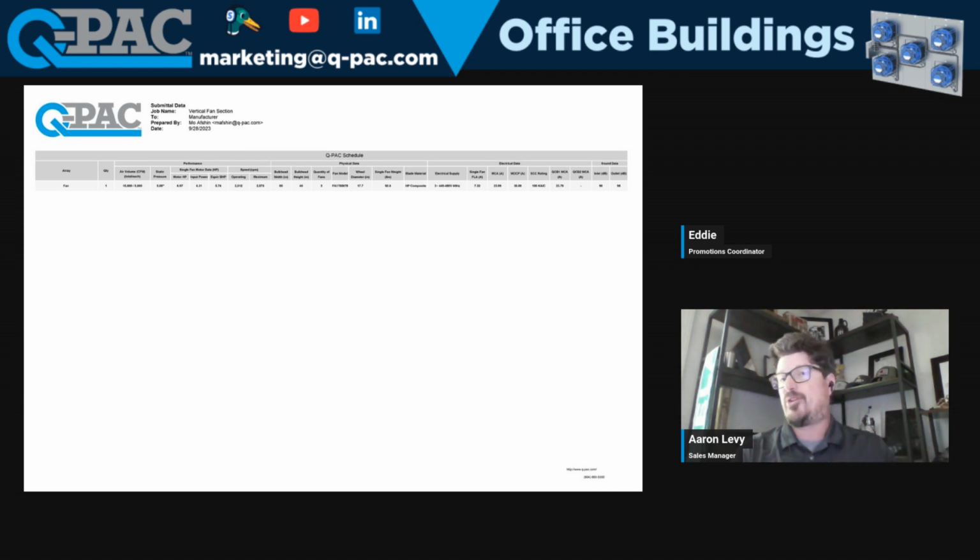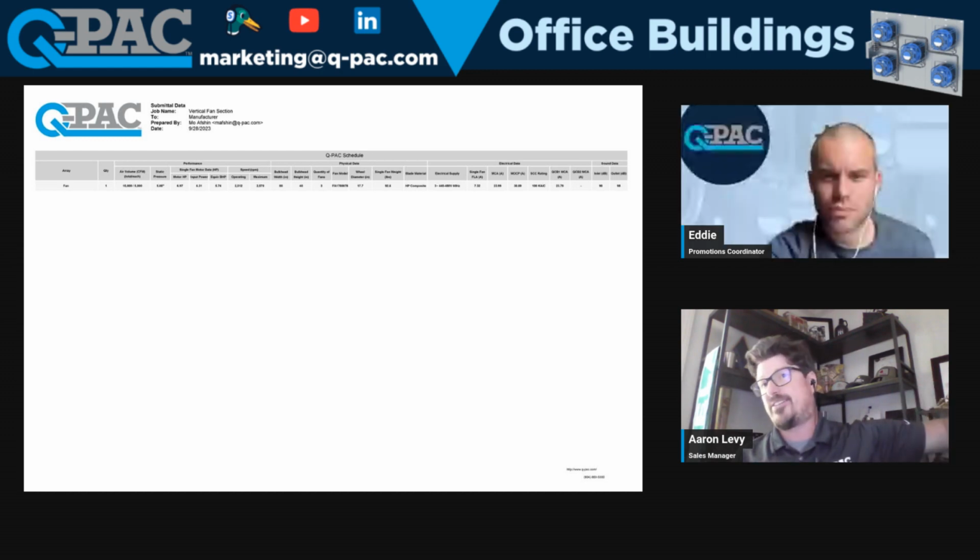It really depends on how many quick connect boxes you have. So as long as, let's say, you have 8 air handlers that all have less than 9 fans on there, the wiring diagram is exactly the same. There's only one terminal block in there that sends signals back to the quick connect box. Because it's a mirrored terminal, there's your line voltage and control from this side to your line voltage and control on this side. They just have to connect those points back to back, and then we handle the wiring from the back side of that terminal block to the fans themselves.